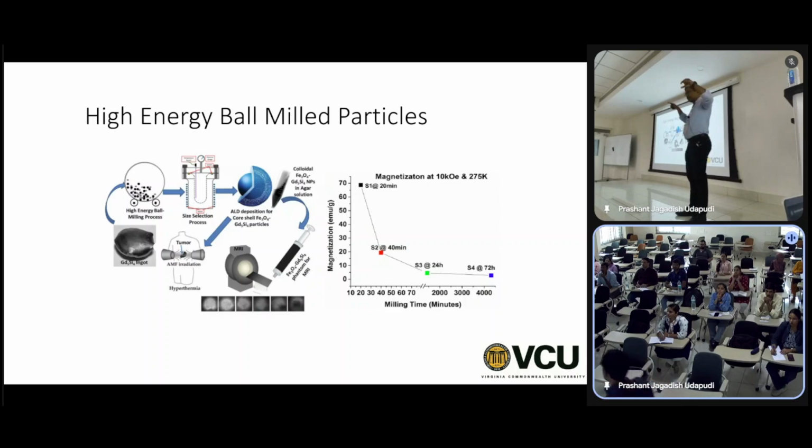If you look in the scanning electron microscope, you'll see some small residual phases of 5,3 or 1,1 gadolinium, silicon, or gadolinium 5, silicon 3 residual phases in the material, right? So you have to maintain the right stoichiometry. Once you have this ingot, you do thermal treatment to get the monoclinic phase.